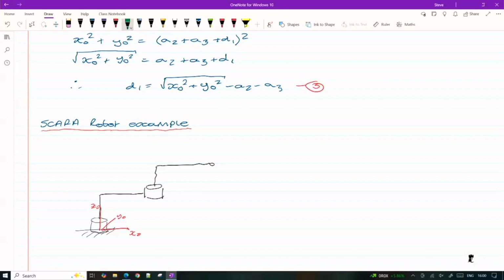I said it's a limited view of the SCARA robot. For a full SCARA robot, and I'm not going to go to that extent here, at the end effector we may have a further prismatic joint that gives us some ability to move a tool tip into and out of our work envelope. So typically a SCARA robot may have a pick and place operation, so it'd have a claw, it'd have a prismatic joint and a claw at the bottom of the prismatic joint at the end. So this is just an extension of the previous diagram. Okay, so this would be attached here